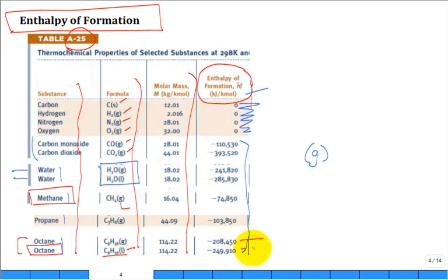These 2 enthalpies of formation are not the same, are they? And what do you suspect? That they're going to be related to the hfg, heat of vaporization, and the molar mass. That's what they are, the difference between the 2 values. Because notice, when we have the hfg, that was on a kilojoules per kilogram basis, so I'll use my molar mass to get kilojoules per kilomole, and then that would be the difference. All right. So this table is very important. In this chapter, you have to go into that table and get those enthalpies of formation.